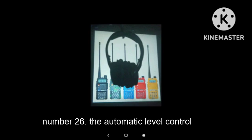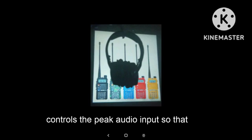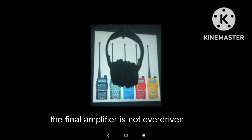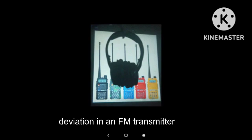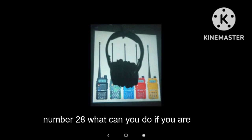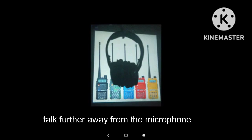Number 26. The automatic level control, or ALC, in an SSB transmitter controls the peak audio input so that the final amplifier is not overdriven. Number 27. What is the result of an over-deviation in an FM transmitter? Out-of-channel emissions. Number 28. What can you do if you are told your FM handheld or mobile transceiver is over-deviating? Talk further away from the microphone.